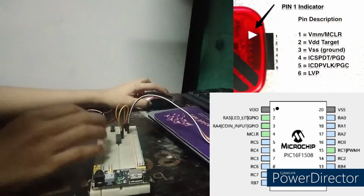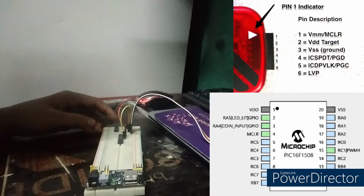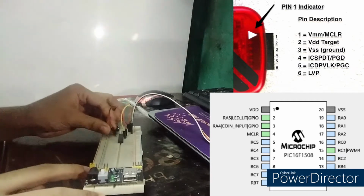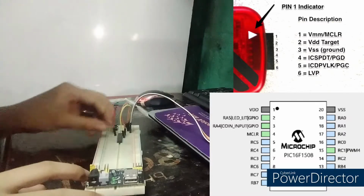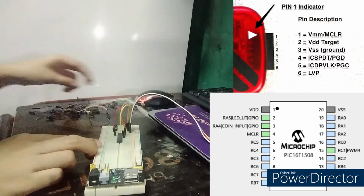The next one will be VSS. VSS is this red wire here. VSS is the ground. So let's connect it here on the 20th pin. This is connected. Our VSS, or our ground, is connected to the 20th pin of our IC. Based on our pin configuration, our LED, or our output, will be connected on pin number 2 of our IC. So pin number 2 will be our output.